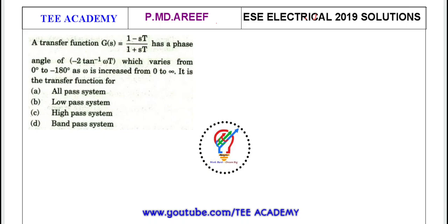Okay, let's start the question here. The first question is: a transfer function G(s) = (1 - sT)/(1 + sT) has a phase angle of -2 tan inverse of omega T, which varies from 0 to -180 degrees as omega is increased from 0 to infinity. It is the transfer function for?